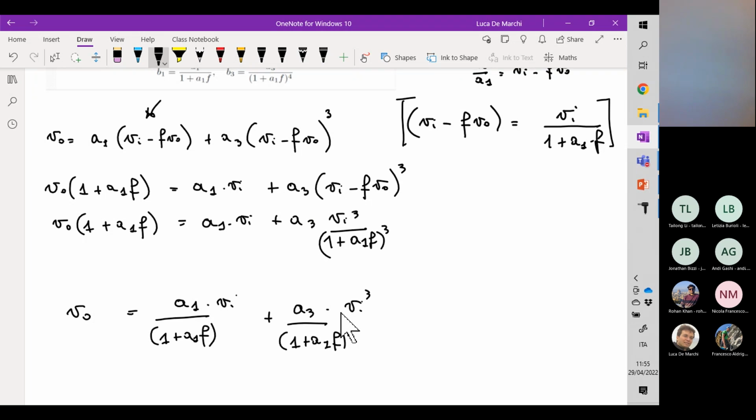You may see that a phase margin equal to 60 degrees is a very good compromise, because a phase margin equal to 90 degrees has a relatively small slope, while the reaching of the final, stable value is much more rapid with a phase margin equal to 60 degrees.